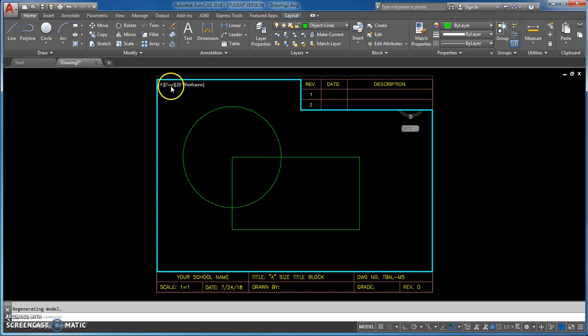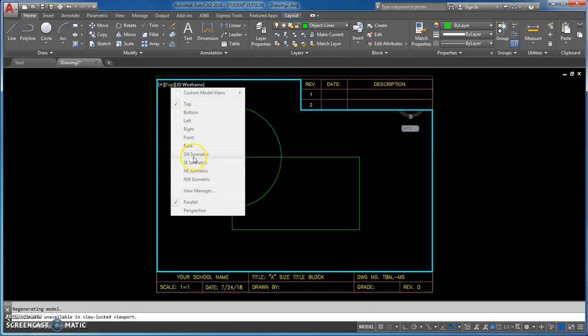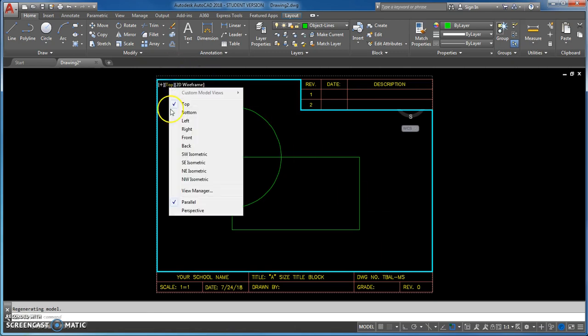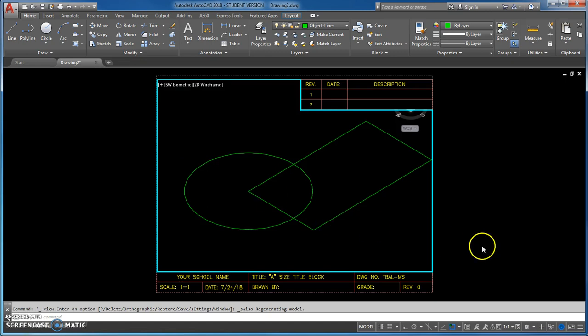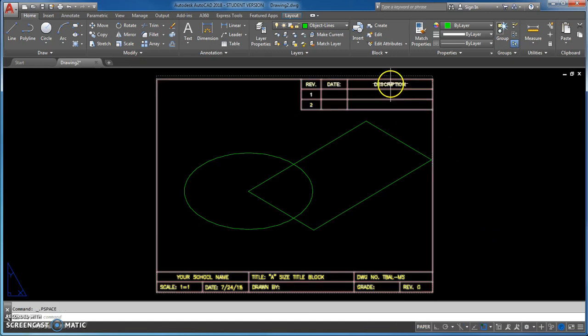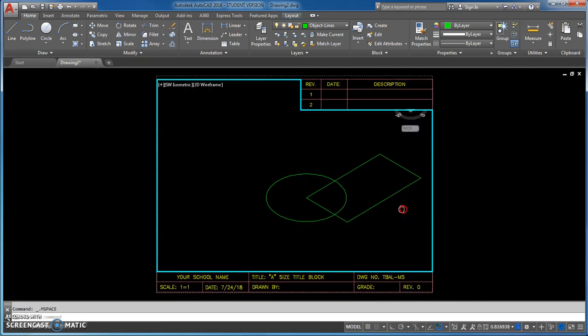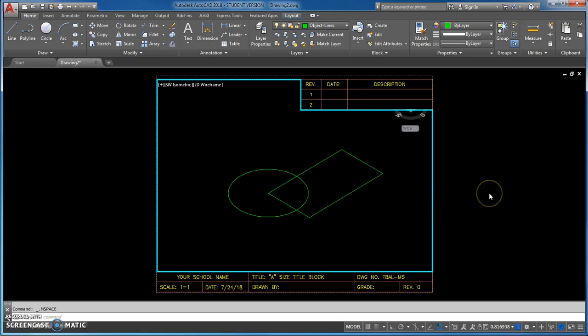and I forgot you got to change here. It's my mistake. Oh, I forgot. This is a good thing. Forgot to unlock it. Okay. Now we'll go back. Southwest. So notice how my drawing view has changed, but my title block border hasn't gone to southwest because it's laying on the sheet of paper. So that's just to demonstrate.